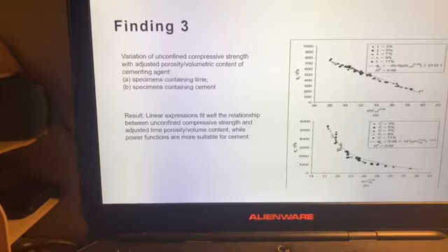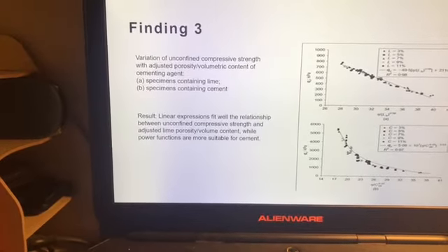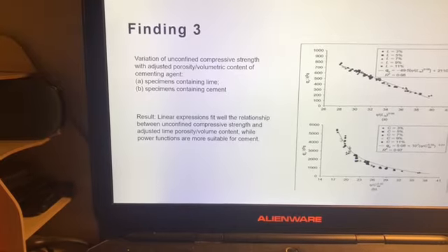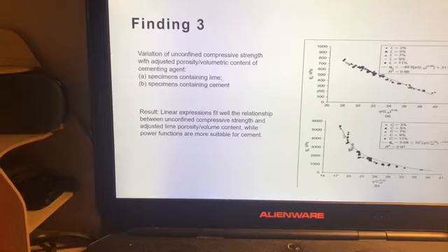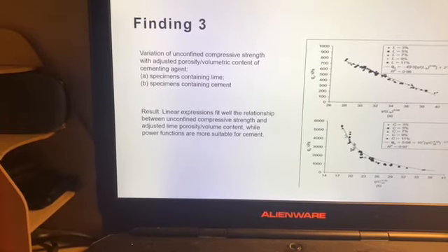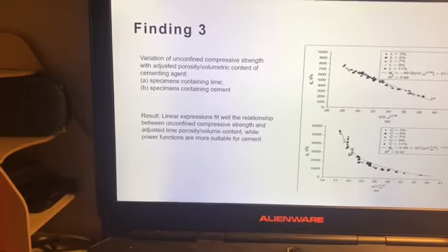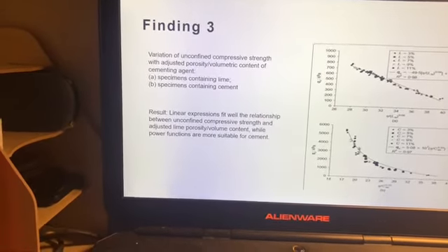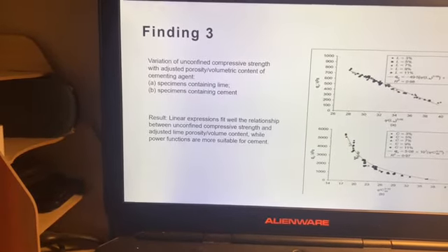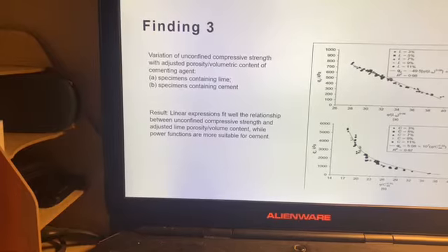The research also found that after taking the soil lime mixture parameter to the power of 0.06, the cement soil mixture parameter to the power of 0.35, and making good adjustments to the unconfined compressive strength data, a good consistency was obtained.